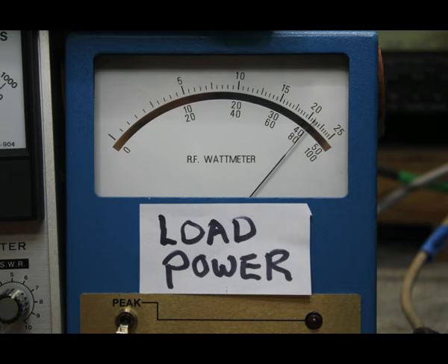Now this 42 watts of power includes the loss in both of the matching networks and the 25 feet of cable. So we can see that we're nowhere near what all these tables tell us the coax loss is going to be. And this proves something. This should prove something to us, at least if we have any ability to look at this thing objectively.